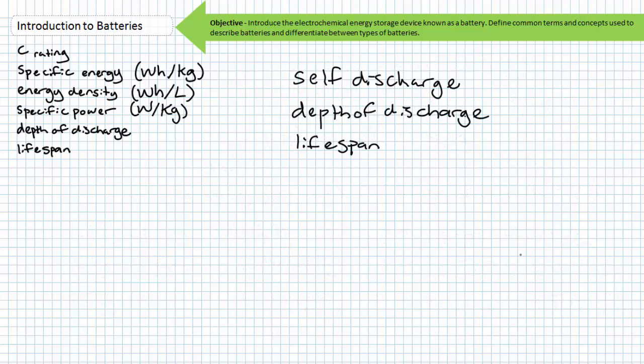While we are on the topic of differences exhibited by different battery chemistries, consider the different safety and durability concerns. Lithium polymer cells with a nominal voltage of 3.7 volts have an annoying tendency to burst into uncontrollable flames when charged above 4.2 volts and/or punctured.